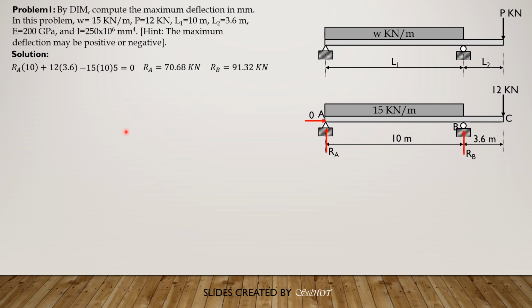So to set up the equation of the elastic curve, which is the moment equation, for this case, we can have one moment equation for the entire beam. So we extend the uniform load here in portion BC and add it with a counter upward load of 15 kilonewton per meter. So that's it. Our origin is A, and X is the distance from the origin to that section.